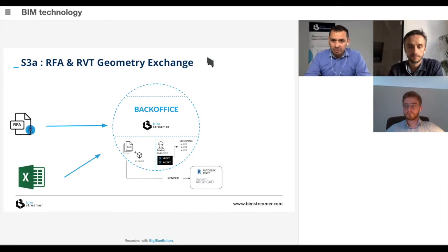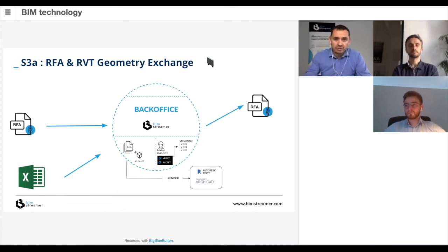This strategy assumes that within the input we have the Revit file. You could consider that an individual strategy because we're preparing the file in Revit, and we can of course use it for Revit. But in this particular case, we will also try to use it for Archicad, because Archicad recently equipped its add-on set with something called RFA RVT Geometry Exchange, which allows us to convert Revit files like RVT and RFAs into corresponding Archicad files.